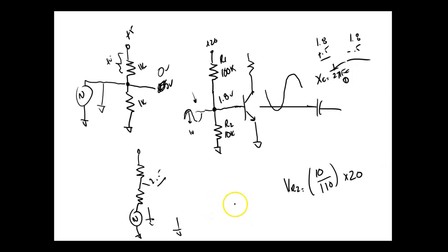In fact, I think I even drew this. So this goes into the amplifier of my oscilloscope. I put the switch down here, it goes through a capacitor. And then I put the switch up here, it goes directly in. So this is direct couple, this is AC. So when I put that on AC, all you're doing is putting a capacitor in series. That's all you're doing. It blocks the DC and passes the what? The AC.